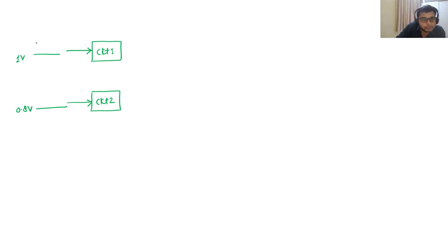So when we drive our circuits with some different circuit on the backside, the circuit driving it can go 1 volt down. Let's say the common mode of that output is 1.6 volt. With a symmetric swing, it can go above to 2.2 volt.